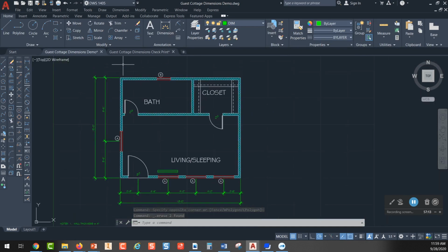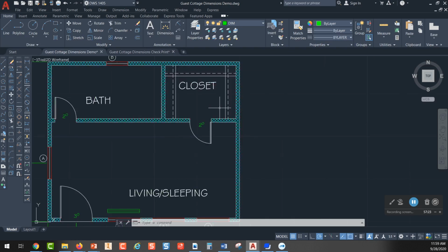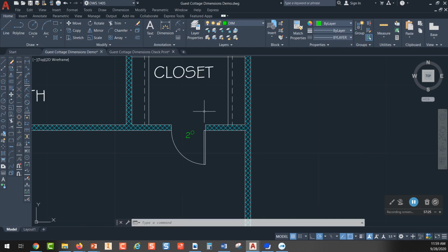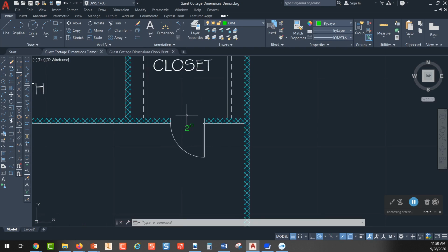Pardon me. I would do the same thing on the top and the right side views. And you can see those dimensions on page 313. And I also need to add these dimensions that I showed you in here. And so to place this dimension halfway between this door jamb and this door jamb, what I would do is pick on my linear dimension.